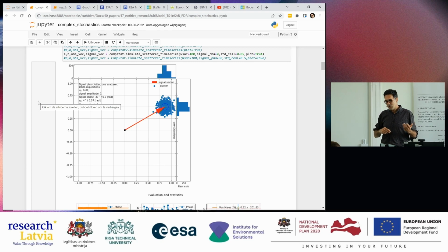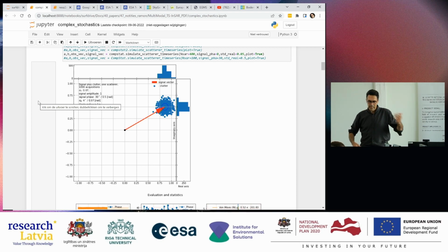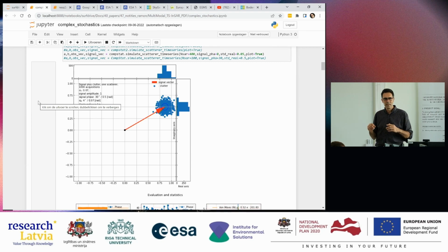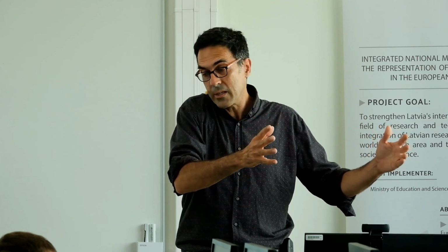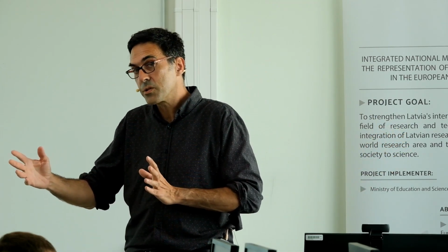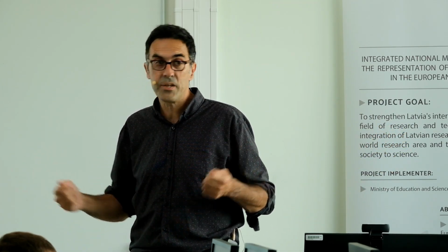So you cannot say INSAR is better than leveling or the other way around, or how does it compare to GPS, because we're not comparing the same things. GPS receivers are always the same thing. You can say something about it independent of where you put it, roughly speaking. With INSAR, every square meter is different. So basically we have to learn to deal with that. We have to learn that some places we get good data, other places we get a little bit worse data, and depending on our applications, we make a choice.